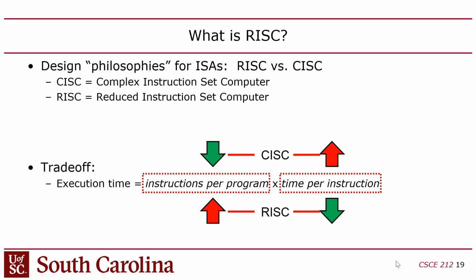Now you might say, wait a minute, I thought you said that there's specialized hardware now in every embedded processor, like the Apple chip. They have whole regions of the chip that are specialized. Yeah, kind of weird, right? Also, RISC-V just finalized their vector extensions, which is kind of cool. It may be too aggressive to try to do that in this class, but they have these vector instructions now. Vector instructions do a lot of work. They process vector operations with one instruction.